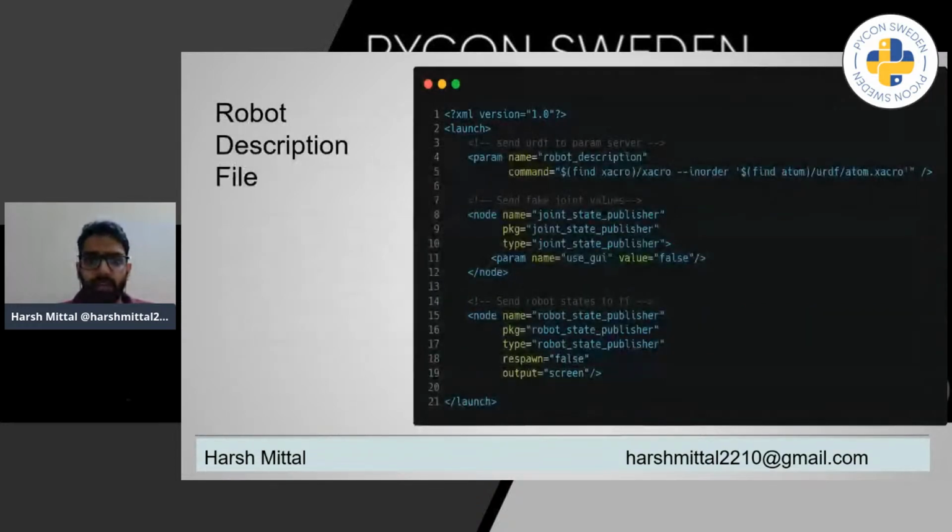Over here, using this line, we'll first convert our Xacro code into URDF. To give you a brief idea, everything related to our visual aspect, our collision aspect, and all the different robot aspects will be defined in this particular file. And by default, the file is used as URDF. We'll discuss how exactly you can write Xacro as well as URDF files later in the slides.